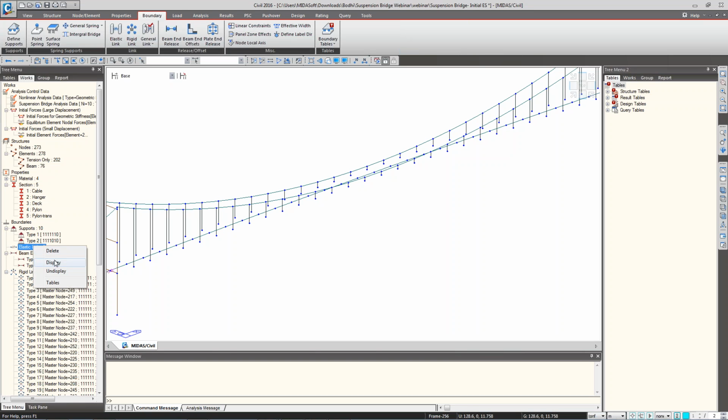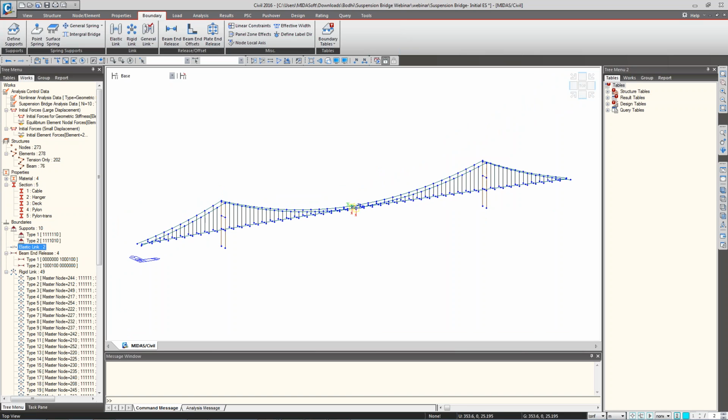So once you have done that, it generates two elastic links for the sag points. So this will be like a central span stay. It will just inhibit any movement of the span of the cable in the X directions at the center span. Okay, so once you have done that, I need to apply other load cases now, because this is my completed model. This is how my model will look at the final stage.